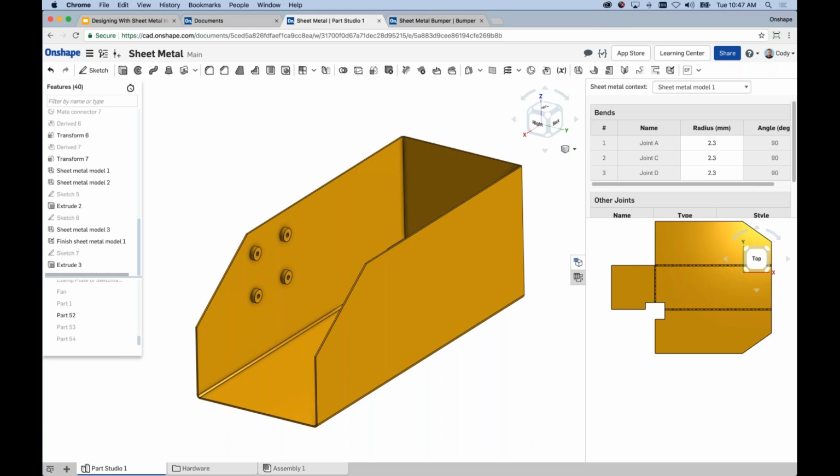Now, sketches and extrusions are a way to start a sheet metal model and also create cuts. You can essentially cut a sheet metal part using the normal extrude remove, and it's not limited to that. You can also do things like Boolean subtract sheet metal parts and other removal. You can remove geometry from sheet metal parts. You just can't merge extrudes and things with it until it's finished. I hope I made that clear. But that's the key reason that you have finished sheet metal.